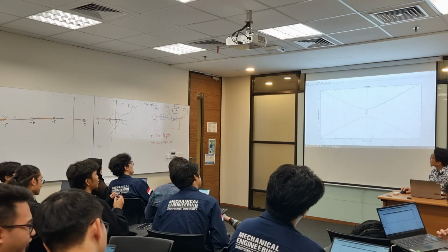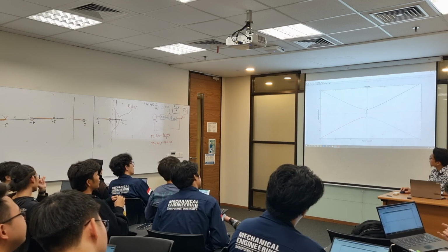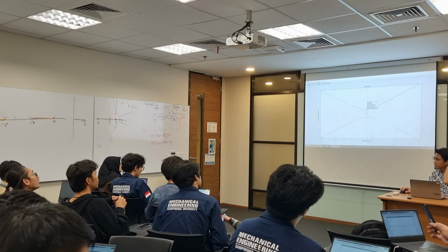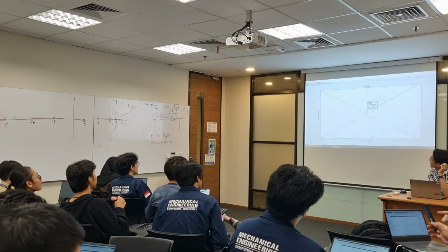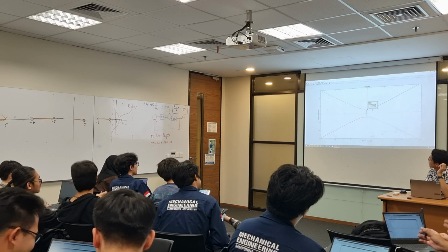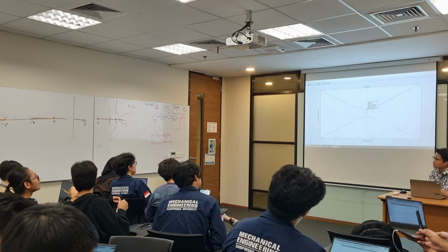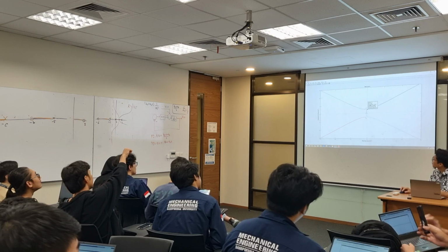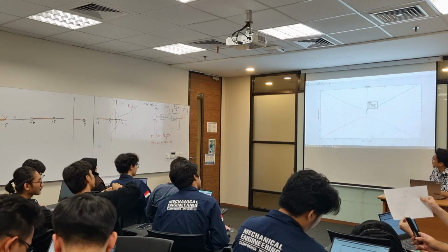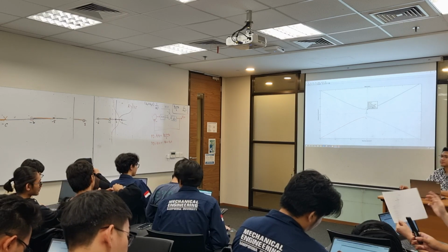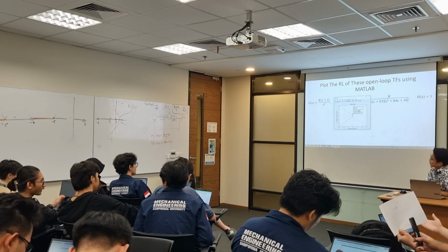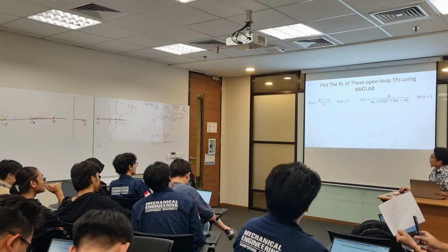You can check the value of K here. Gain 24.9, it is still stable. Starting 26 point something, that's unstable. You see the pole is already positive there. Gain 26, it is still stable. Okay, next.